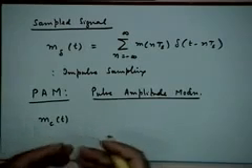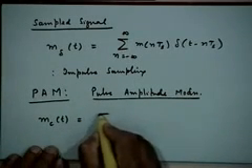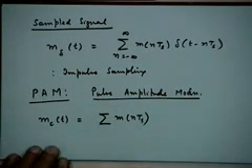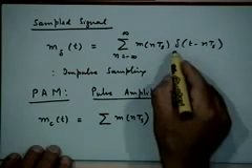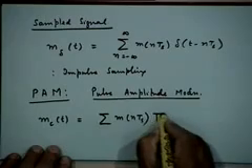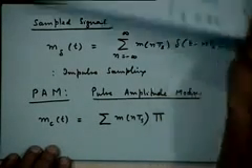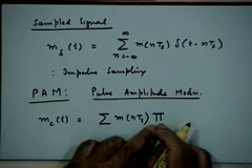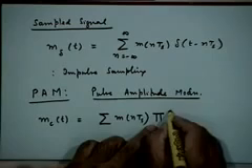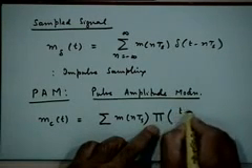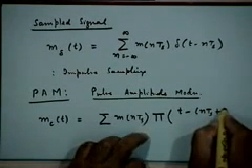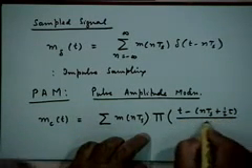So, the sampled signal in this case is denoted by m_c(t). C denotes the carrier. The carrier is a pulse train here, and that will be the same thing as this, into, instead of an impulse function, a rectangular pulse function, right, of the kind that I drew here. This is a notation for a rectangular function. Instead of writing rect, sometimes we just use this notation to denote a rectangular function with some argument, and the argument is (t minus nTs plus tau/2) upon tau.